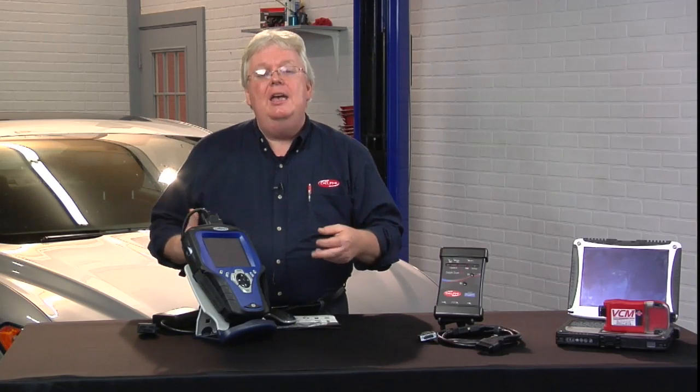But definitely, cylinder misfires, if it's a Ford and it's not spelled out in data parameters, does not give you, like in a Tech 2, a bar graph of how bad which cylinder is missing and so forth. The P0440 is so ambiguous that it's like, well, you have that problem, give me some more information. Definitely mode 6 is a must there. P0420 comebacks we talked about with the CAT efficiency, looking to see how close we are, and hopefully we didn't miss the mark on that. So all the above is the correct answer.